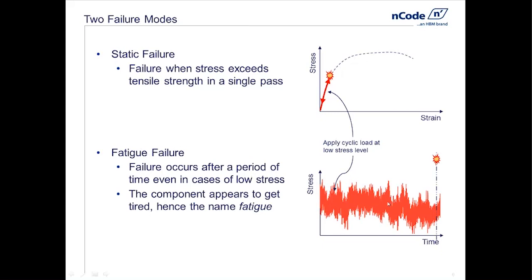The stresses continue to change repetitively because of vibration, because of temperature change, because of loading and unloading, because of turning, because of hitting bumps, taking off, landing, and so on. So whatever caused the stress to change, it never gets that high, but if enough of these fluctuations or cycles occur, we may have failure happen over time in a way that we would not have expected simply looking at static failure criteria. We call this fatigue, from the French word for being tired.